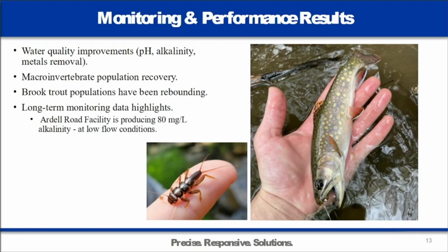Likely that is higher because in a dry time like now, when I was up there a couple weeks ago, the systems were not flowing because the streams were at the lowest part. So we're seeing around 80 milligrams per liter production out of these systems, which is very close to the designed values. So each system on average is producing, obviously the intake water, the more acidic your intake water is to the system, the more dissolution of limestone you're going to have.